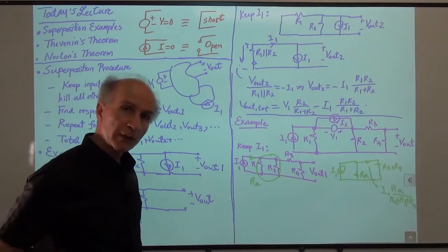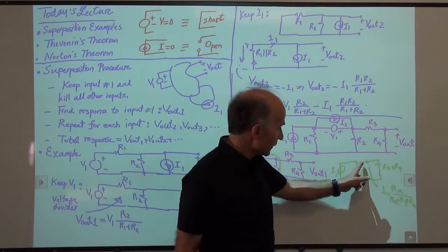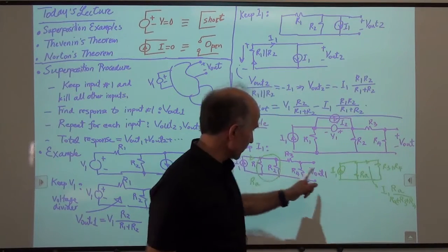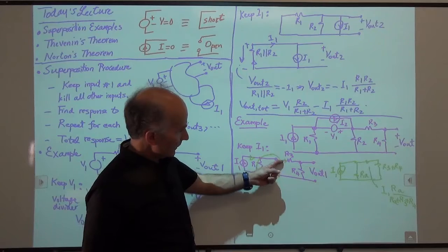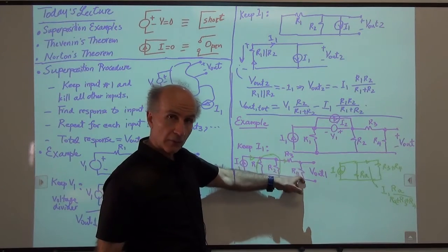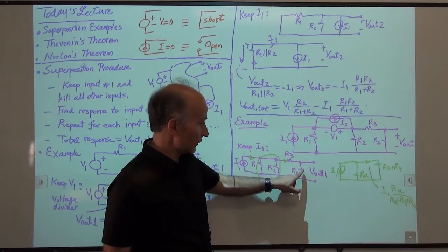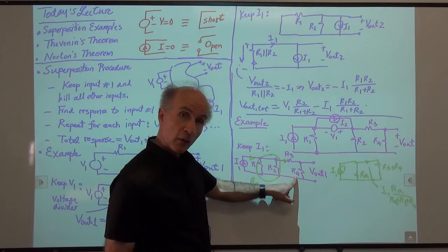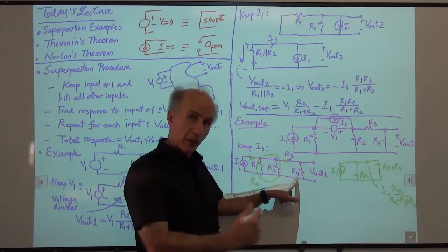All right, so what did you get? Okay, well, what we see is that this current is flowing through these resistors. So that's the one that we have found right here. This current goes through R3 and it goes through R4. So if I want to find this voltage, which happens to be the voltage across R4, Ohm's law says multiply the current flowing through R4 by R4.